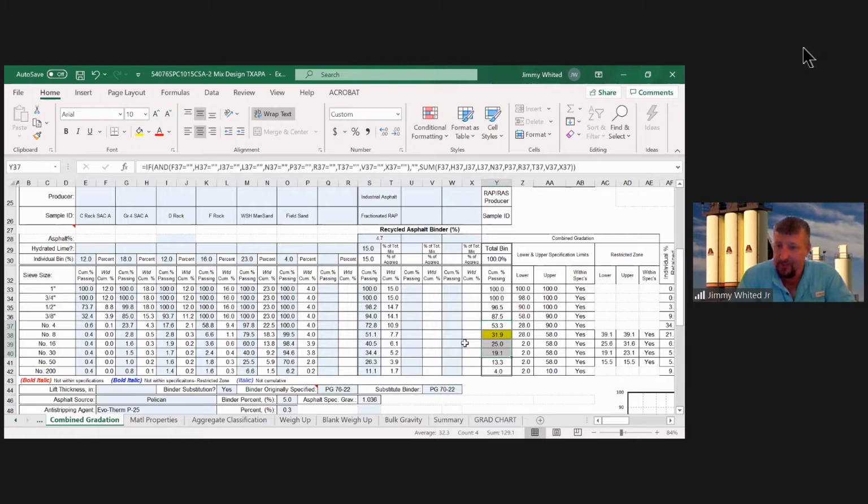Superpave mixes let you go up to a 7.5% bonus. So getting that consistency is big, because now you can't deviate by more than 1.3% or it's remove and replace. So taking your mixes, pushing that to below that 37 on the type C or below 40, you have to still find your sweet spot.